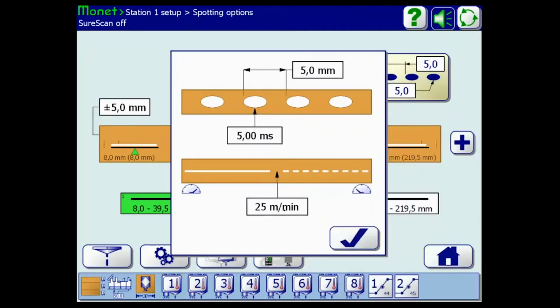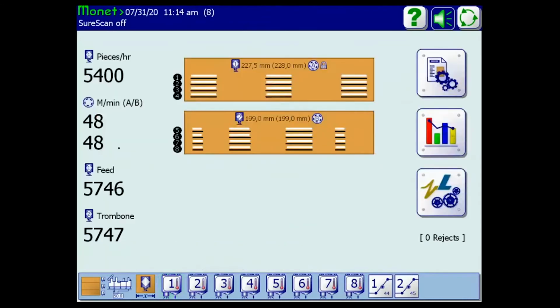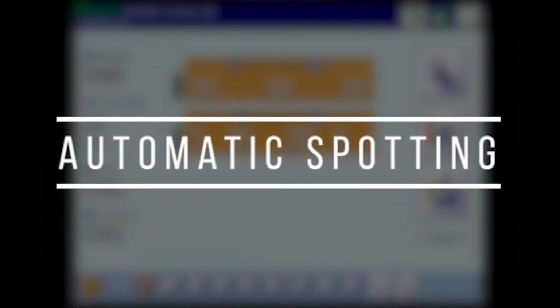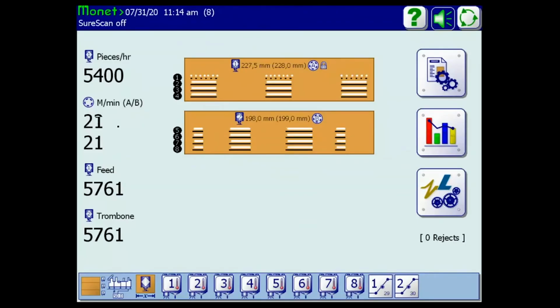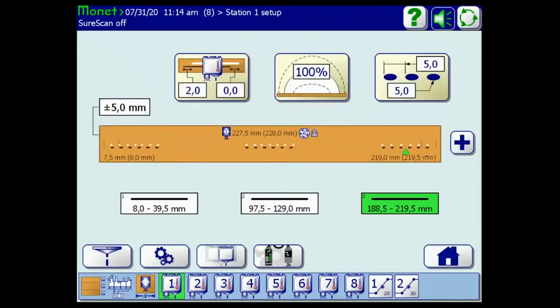if I program a speed within this parameter here, our auto spot speed parameter, now even though I have solid lines programmed for my 3 events, if I were to slow the machine down to that speed reference I just programmed, or below it, let's see. Okay, so I just dipped below 25 meters per minute. And you guys see what happened to glue gun number 1? It went into what we call a spot mode.